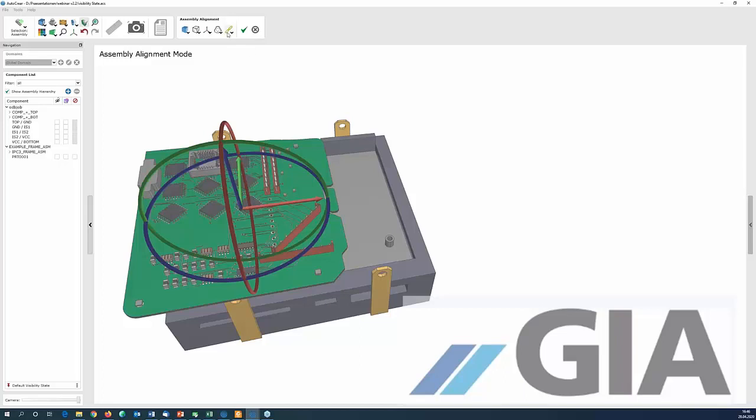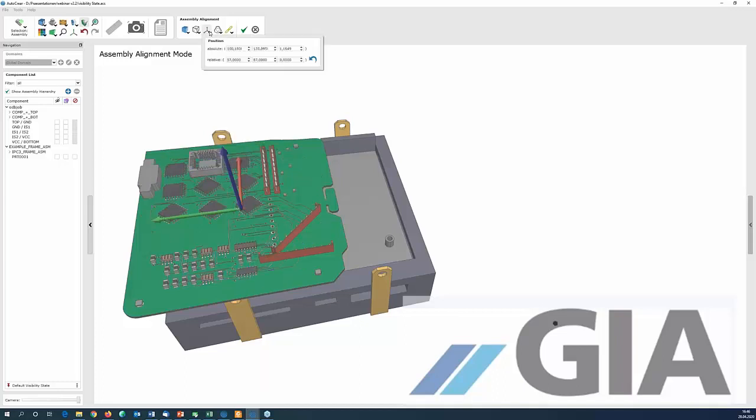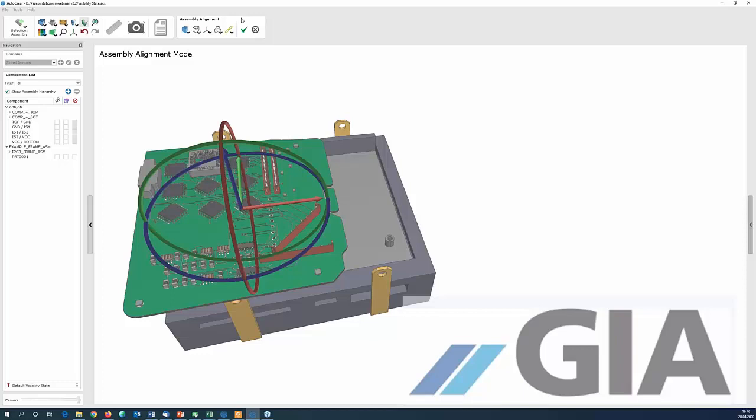And for that, we introduced some snapping functions. What you also could do before is type in the exact translation vector here when you know what is the exact vector between this reference position here and the reference position in the moving object, then you could type in here, but I think this is rarely the case.